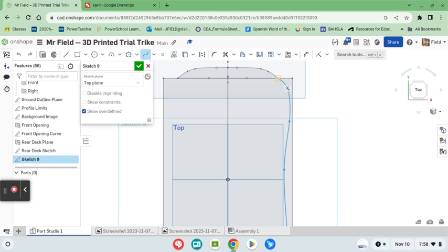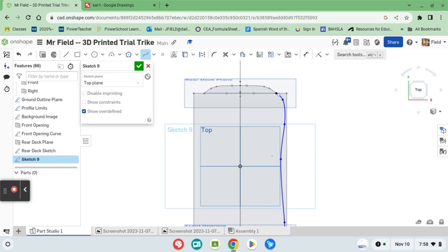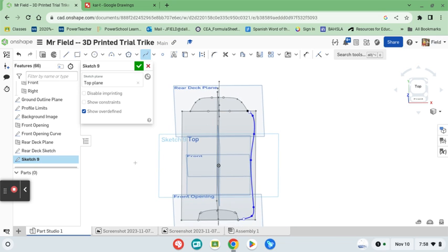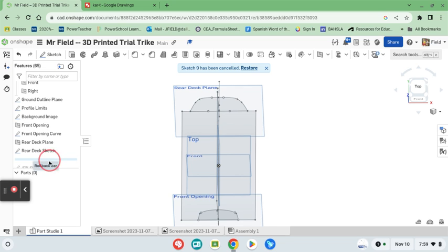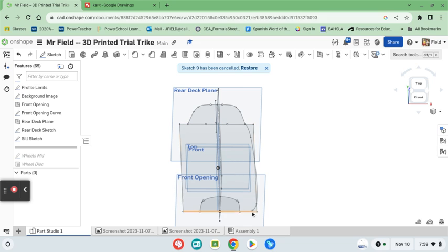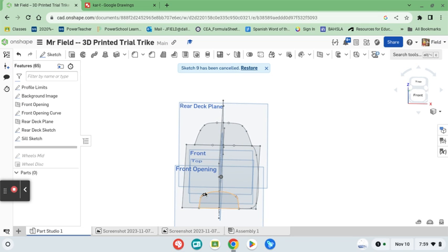And then I'm going to double click right there. So you can see that the spline to do that curve is a total of 1 at the start, 2, 3, 4, 5, 6, 7 total points on that spline. And then I'm going to not accept that because I'm just going to unshow the one that I did create there. In this case, I was going for a smoother look. So I had a total of 1, 2, 3, 4, 5 splines that I used on my ground plane.